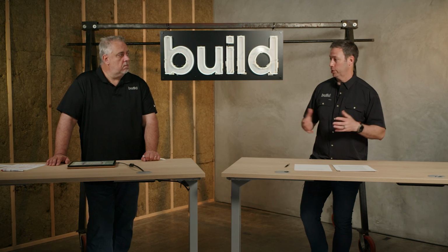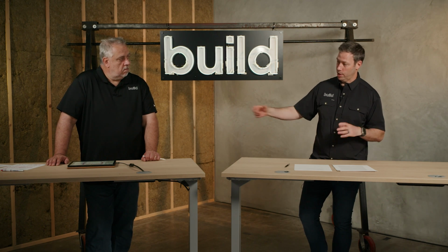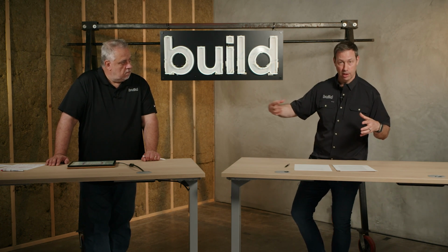Yeah, it might be cold in Minnesota because it's 10 degrees outside, and inside the house is warmer and moister because we've got people breathing, we're cooking, we're showering. And so that 1-inch hole in the drywall, as that air moves through that 1-inch hole, now all of a sudden we can have moisture problems inside the wall.